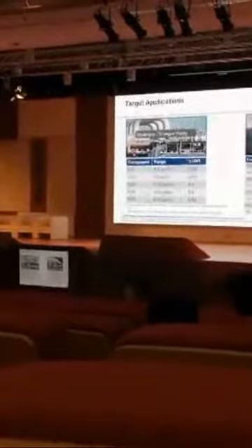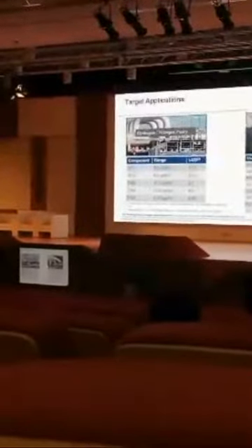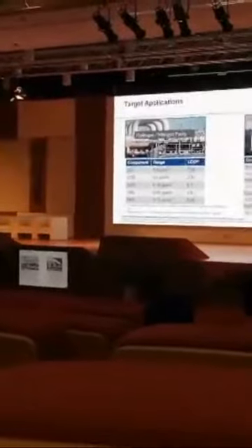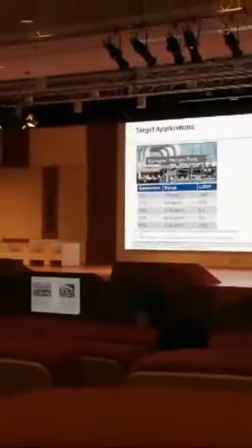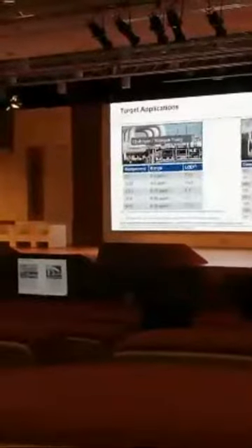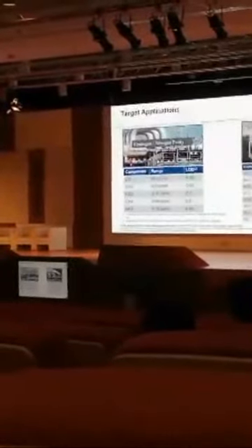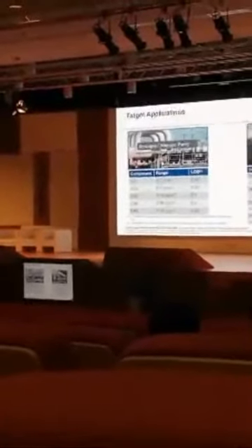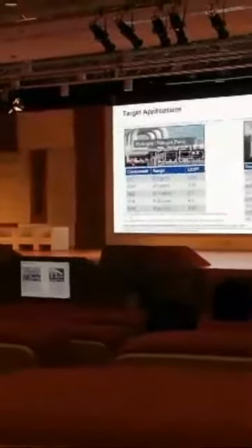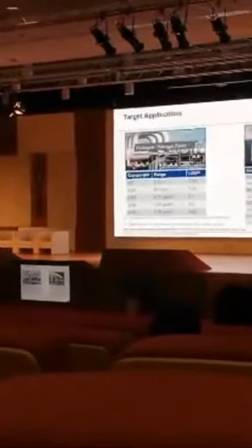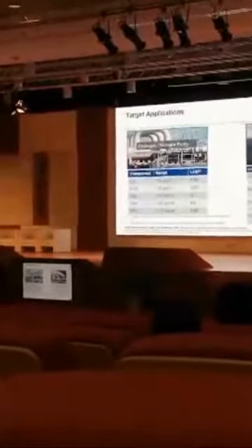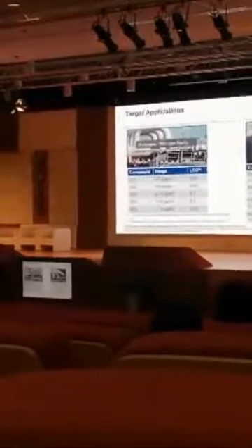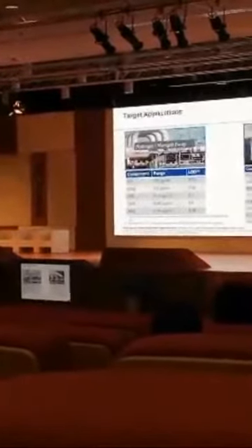The next application is purity of hydrogen and nitrogen. As you know, we have to use either an IR analyzer or a gas chromatograph for such kind of measurements. It requires a lot of utilities. With NDIR analyzers, you may have to perform zero calibration almost every day. But using a QCL analyzer, you would be able to reduce that frequency of calibration by quite a bit. In fact, if you look at such measurements, the readings can be stable for over a year without any calibration. So this is something which we have demonstrated, and as you can see, we have really low levels of measurements.